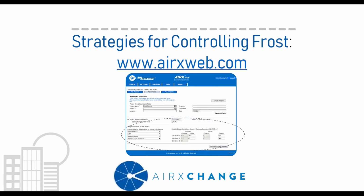www.airxweb.com. Once you open up the software, you're prompted to create a new project. As part of that process, you're going to enter into the software your location and operating conditions. You would then add a wheel to the project, and if these conditions result in frost, the program is going to alert you to that and provide the frost threshold control point. And if you're using preheat, it would also provide the requisite heater size as well.